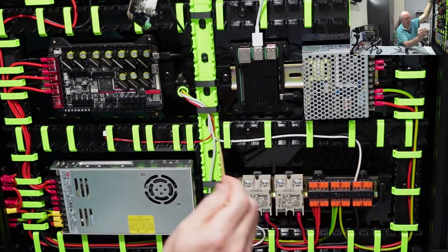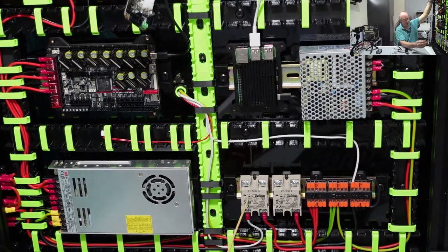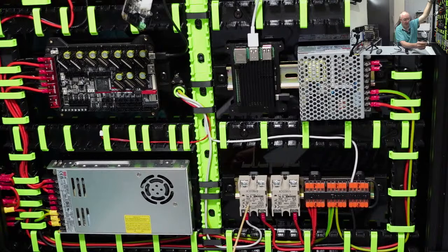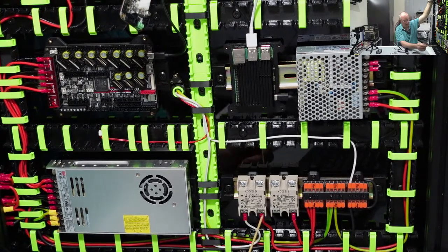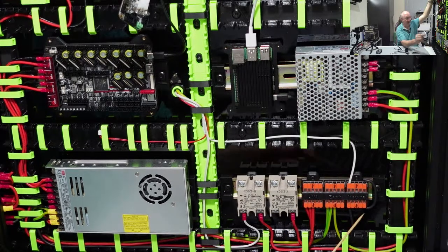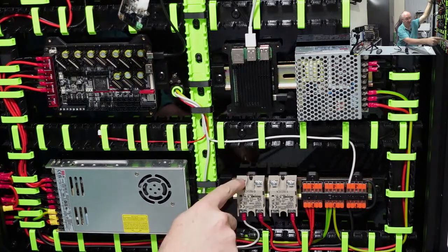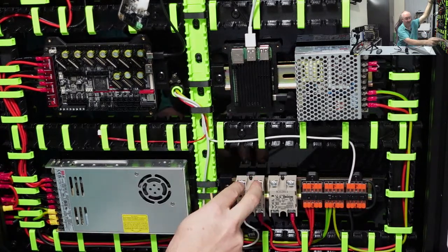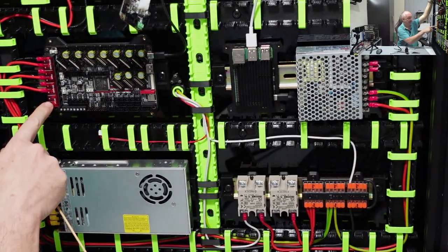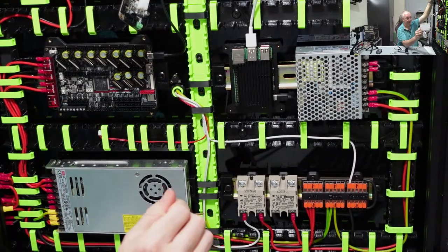Then the other wire is coming in and it's going to the SSR, right, because the SSR is what's going to switch it on and off, and on the other side of the SSR that goes through to my line, right, which then closes the circuit to give that heater AC power. And the DC side of your SSR, you connect that to your bed out connector, right, and that will control your bed heater.